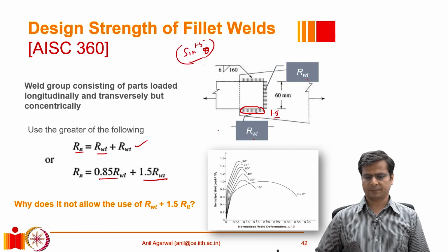So either you can use both of their full shear strength, or for the end one, you use the full tensile strength, which is after amplifying for that factor, but then you have to reduce the strength which is available at the other weld.